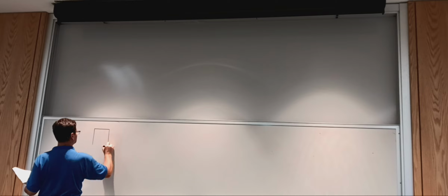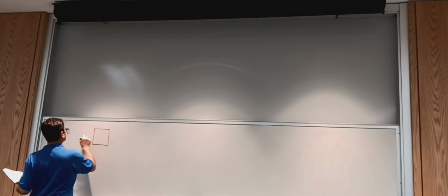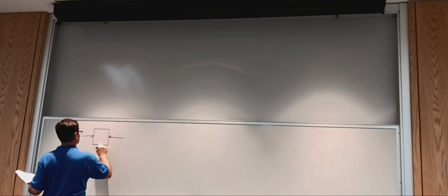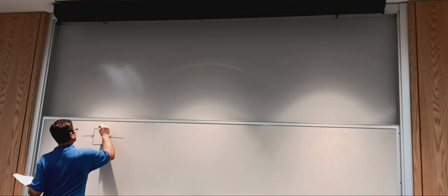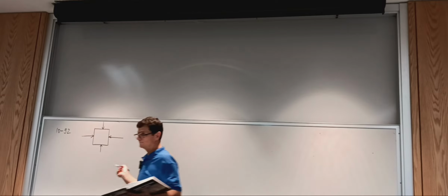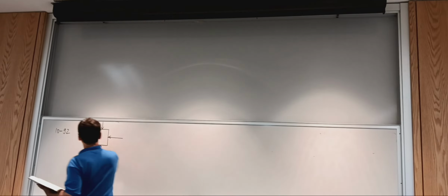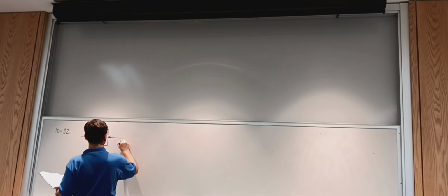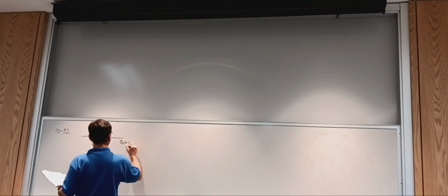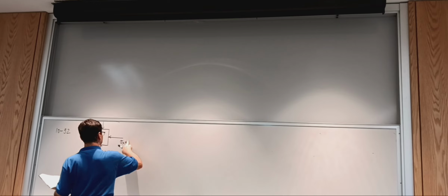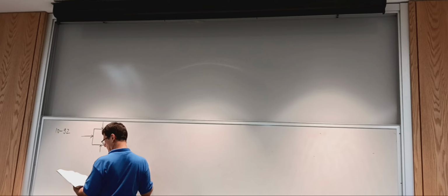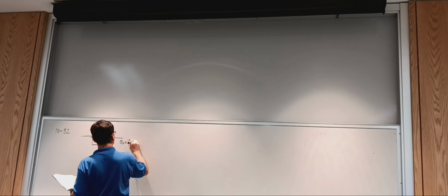The original stress element, we like to orient the part in a convenient way. Usually x is the long axis of the element. So we have sigma x. I don't put a negative because I represent the stress towards the surface, 840.